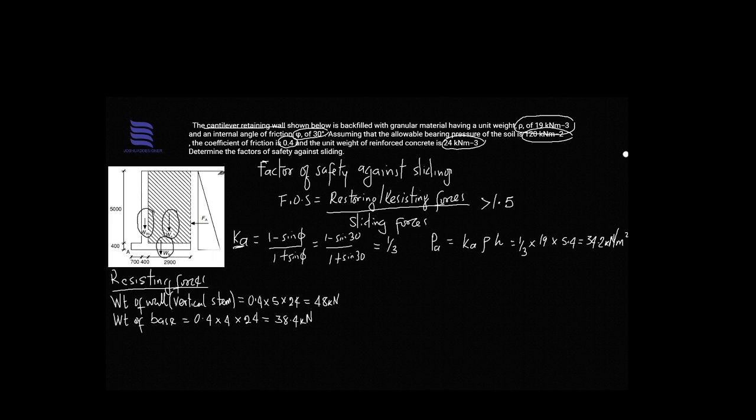Then we have another one which says the weight of the soil. The weight of soil itself now, which is the backfill material, is going to be the width of that backfill of the heel. Now I told us what heel means in the last video. Please, you can check to identify the parts of your retaining wall so that you can follow along as I speak about them. So the weight of soil will be the width of that backfill side of the retaining wall.